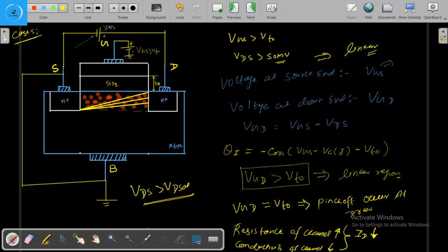So when we increase the VDS by a large amount, we will see the bend in the ID-VDS characteristics, and this is because of the increasing channel resistance. So we can say that in the linear region, the MOSFET is behaving like a voltage controlled resistor,